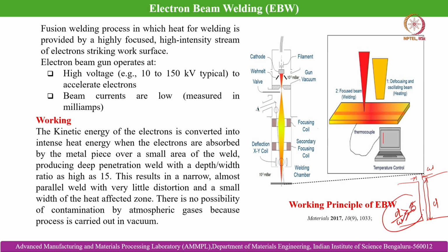So, in this case it is way ahead of laser beam welding, because please recall that we have discussed that in laser beam welding there is a thickness restriction, because beyond a certain thickness the autogenous nature of laser beam welding fails to fill the joint with the enough weld metal which is necessary for developing a strong metallurgical bonding between the faying surfaces, whereas in case of electron beam welding, being a much stronger focused collimated beam, it can weld very narrow and deep